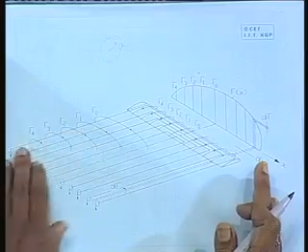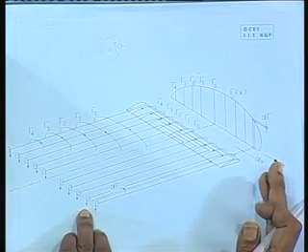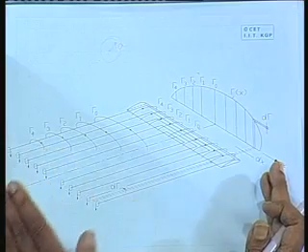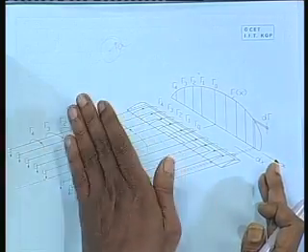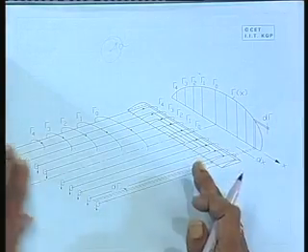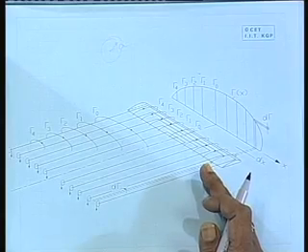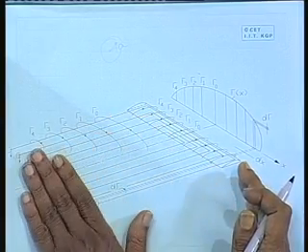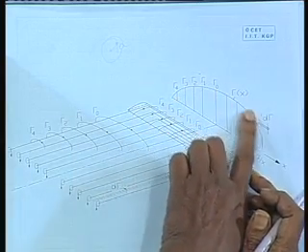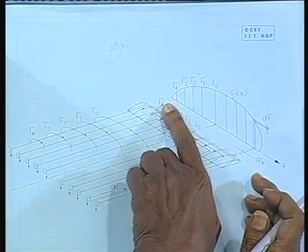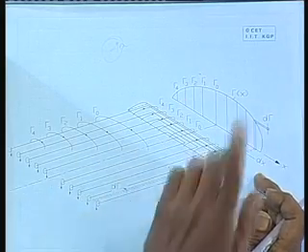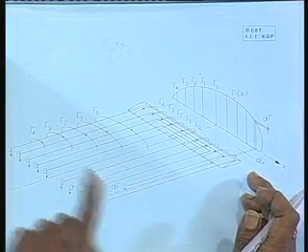So, instead of one trailing vortex at one end and one trailing vortex at the other end, you have as if a vortex sheet. A trailing vortex sheet is produced, and there is a starting vortex. Now, as the propeller moves forward, the starting vortex is left behind, we can ignore it. What we have is a trailing vortex sheet which is created due to a distribution of circulation along the propeller blade, and this circulation creates the lift. We will not go further than this. My purpose of giving you this theory is only to introduce you to how circulation is generated around a propeller blade.